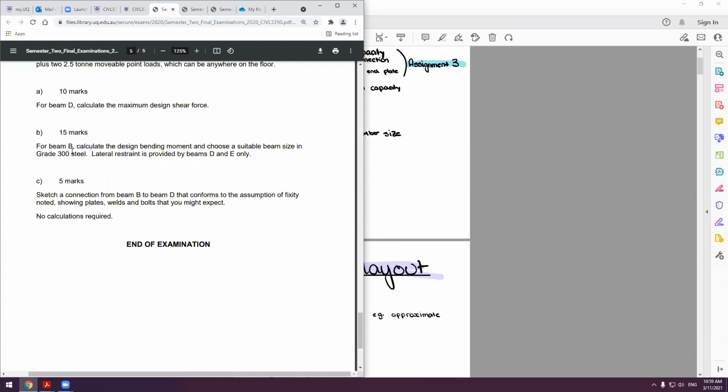So we're trying to find an adequate member for that. So that's what that 1.5 information is, of how much it's going to be reduced by. So it's always approximately 75% depending on how many you use. When you get your member selection, it doesn't need to match that. It doesn't have to match. It's just an approximate. So that was to get the original member.